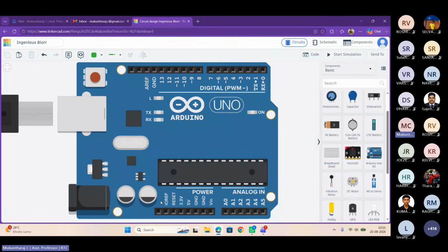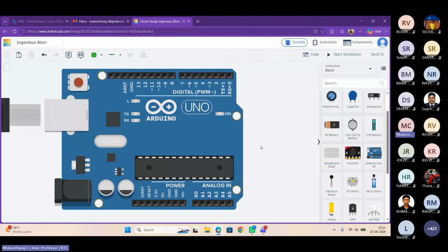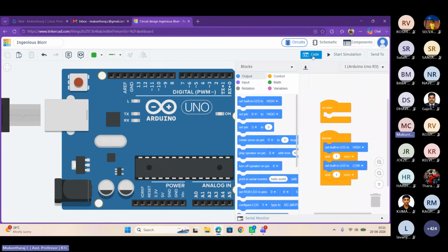And this group of pins are power connectors. We have ground, 5 volt supply, 3.3 volt supply, and the external reset pin. If we need to provide power for the external devices which we are going to use, at that point of time we will be using these power pins. So this is the very short thing we discussed yesterday. And yesterday we had seen the blinking also, correct?